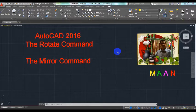In this tutorial, you will be learning the basics of AutoCAD. I want to show you in this lesson how to use the rotate command and the mirror command.